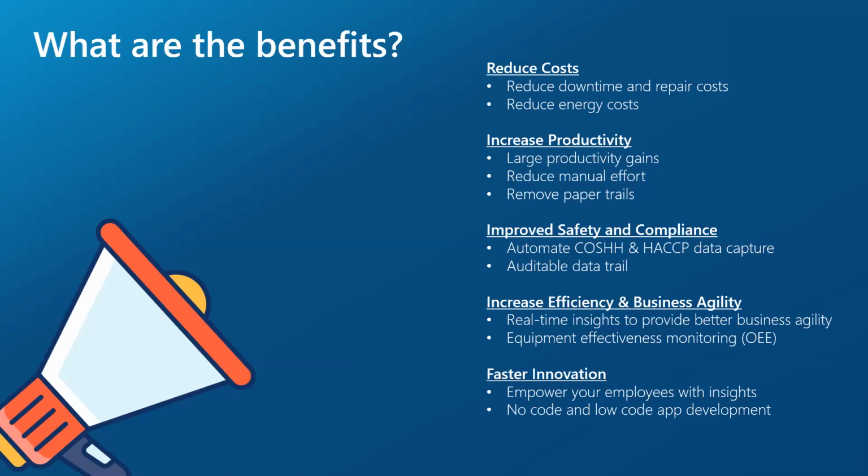That information can help you to identify which assets perform better or worse and use that information to determine whether you need to spend any money on fixing machine tools or whether you need to change your maintenance strategy, or whether it can inform your capital investment into your machine tools.